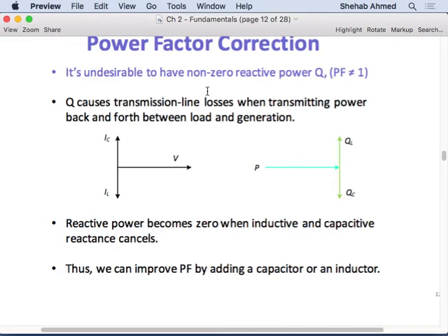So what people do, RasGas for example, they would have these capacitors because RasGas is dictated by Kahraman to maintain power factor at a certain level. So they have to add these capacitors, but if their load changes, they switch them in and out. They have capacitor banks with different values of capacitors that they switch in and out. That's one. It's a mechanical switch.